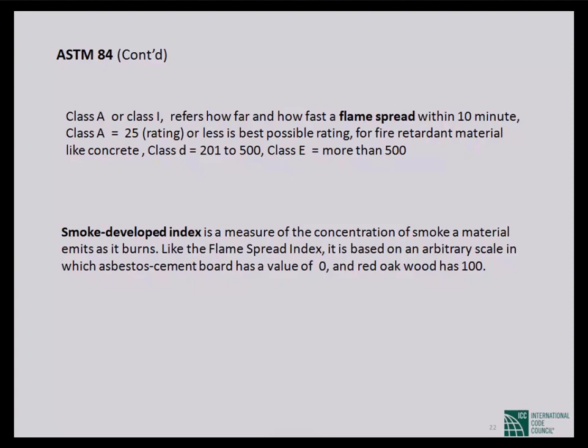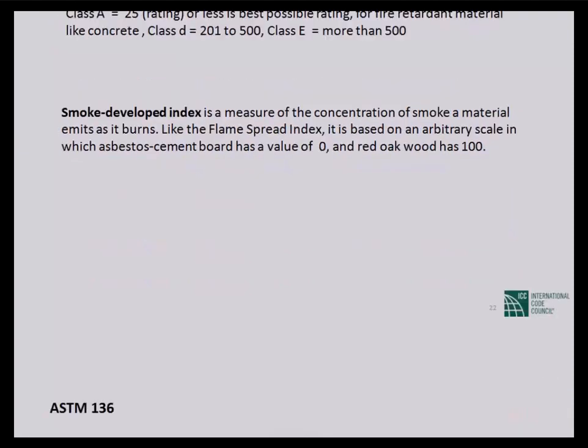And the smoke index again is 0 to 100. 0 is concrete, or asbestos, and 100 is the red oak wood. So comparing these two, all the surface finishing elements or the combustible building finishing elements used in the building are rated, and accordingly they will be used for different buildings for the inside finishing.